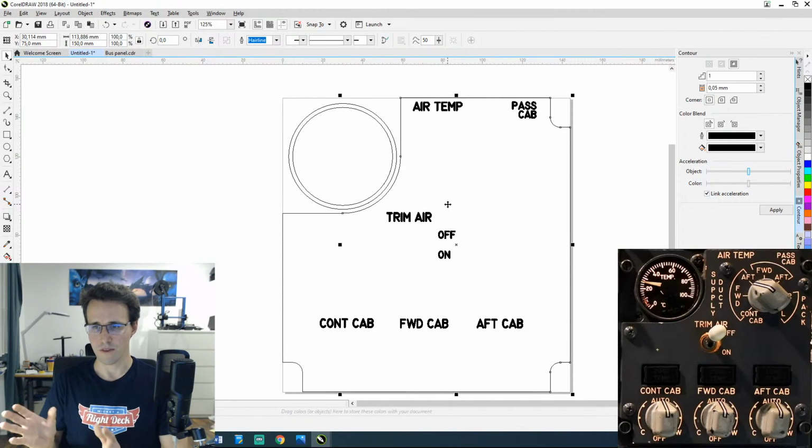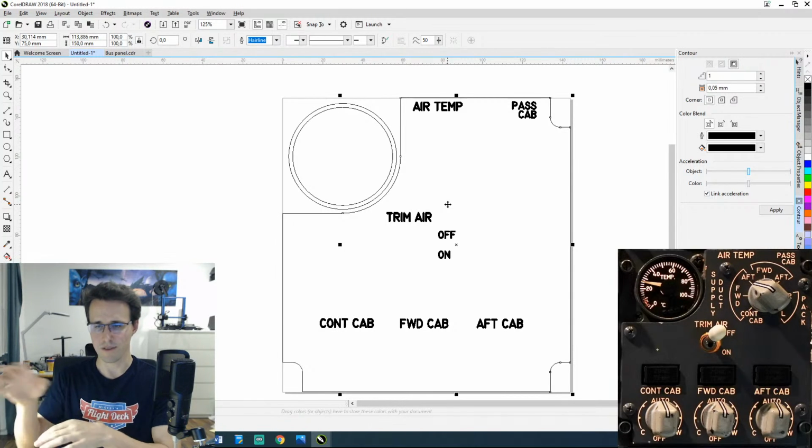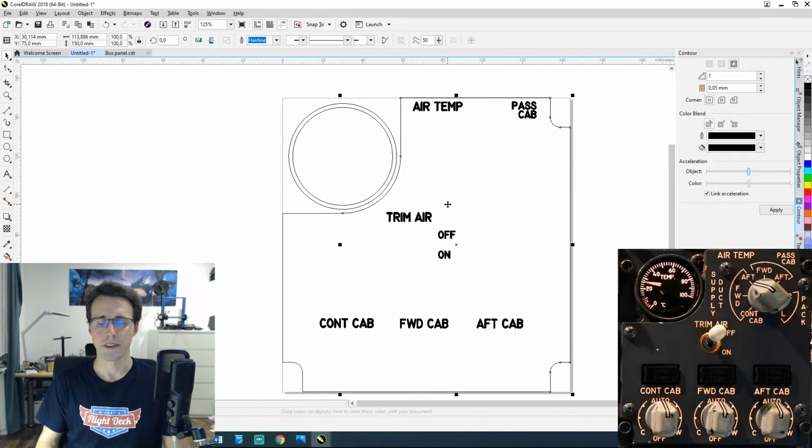There's nothing around it, just the material and the router bit, and the laser has much more around it. It's much faster, laser engraving, but you are not as precise when it comes to engraving to depth, like on the CNC. You can't say engrave this area, for example, 0.5 millimeters deep.